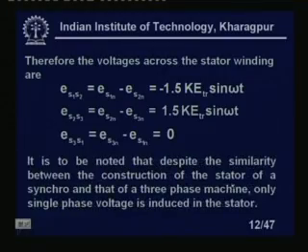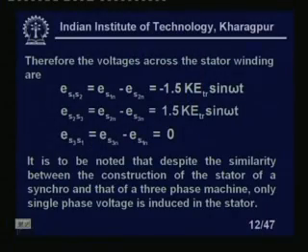It is to be noted that despite the similarity between the construction of the stator of a synchro and that of a 3-phase machine, only a single phase voltage is induced in the stator.